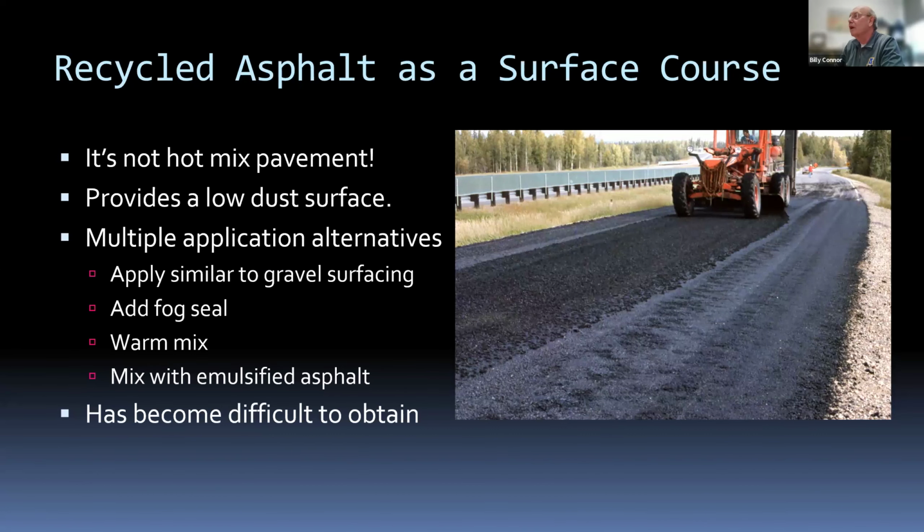Okay, let's shift gears a little bit and talk about recycled asphalt. The asphalt right now is 100% recycled, in one form or the other. DOT does everything from mixing in to the existing base course to mixing in the hot mix, but sometimes we have extra material and we stockpile it, and we can use that recycled material as a surface course, which provides a low dust surface.